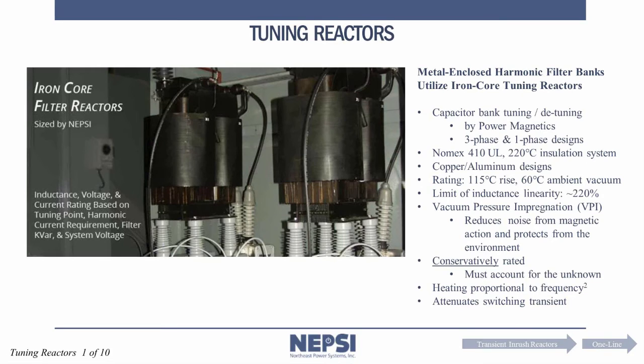What that allows is for the insulation to not be stressed if we put the reactors up on insulators. So we basically tack the incoming winding, the incoming line, to the core, which raises that reactor up in voltage, and therefore the normal voltage during operation across this insulation is on the order of 500 to 1,000 volts.